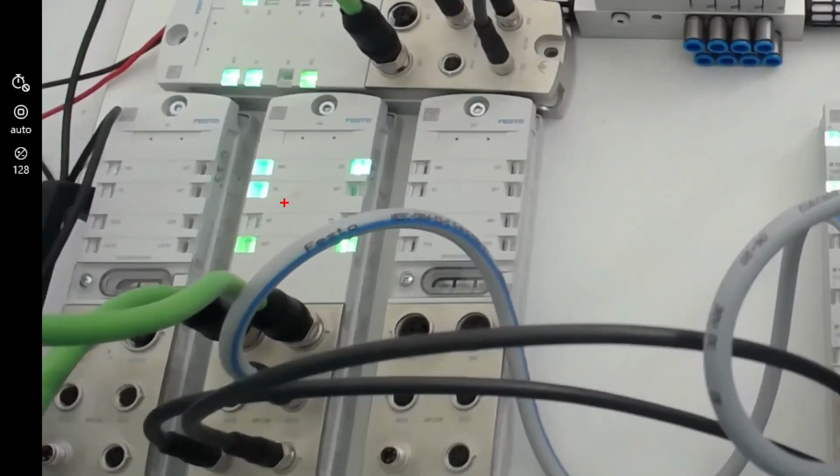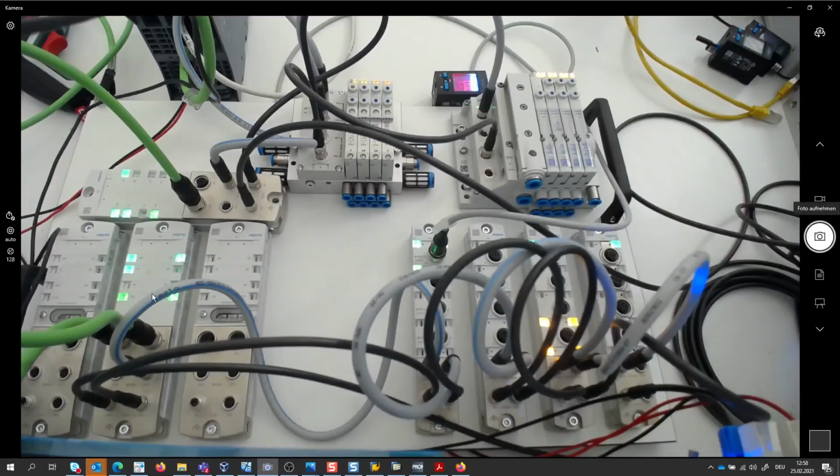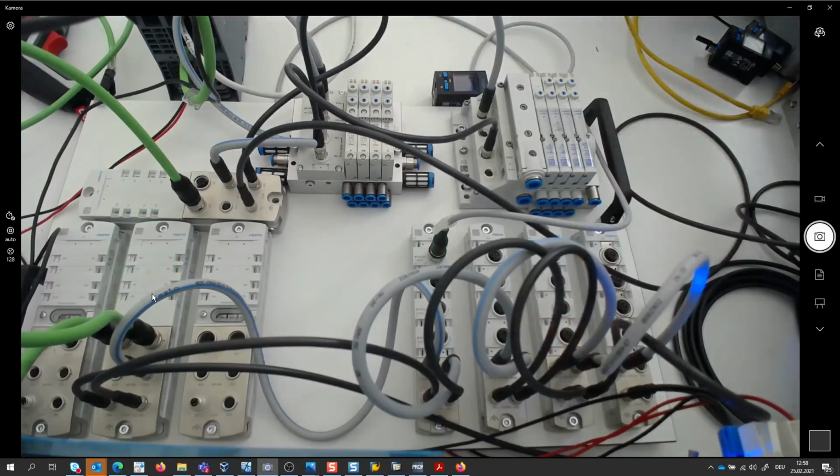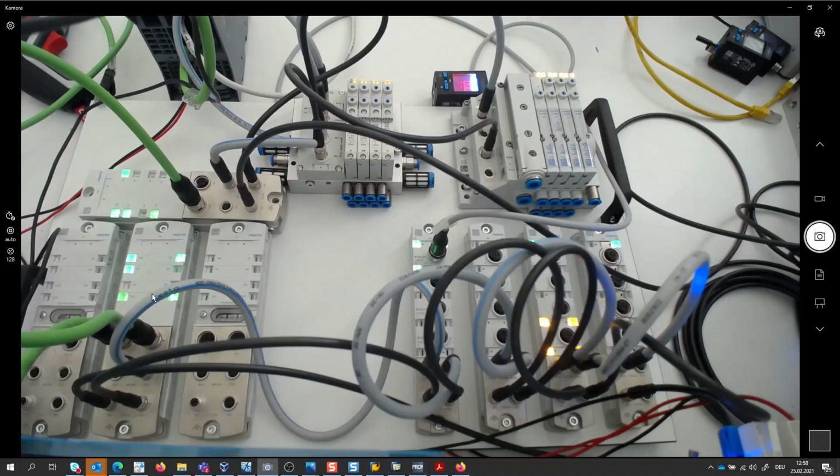This is again the first Profinet slave and this is the second Profinet slave. Without any fast startup option, you will recognize here that we need around 5 till 10 seconds after a power return. So you have recognized, hopefully, this was around 10 seconds till the coils are switched on and both my Profinet slaves in daisy chain are back.